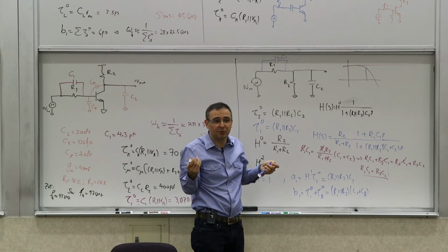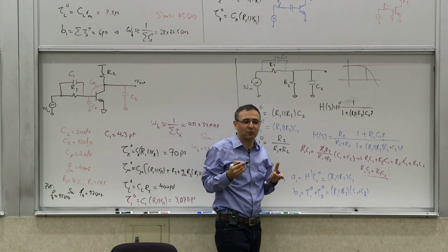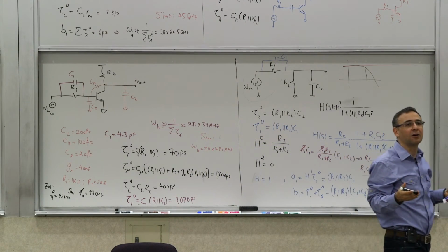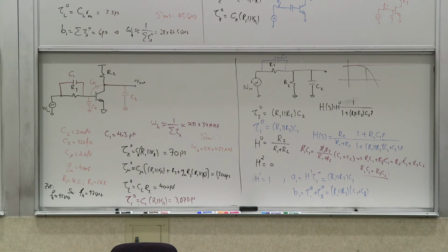And this is another example where it's not just that if you're adding more capacitance, the circuit's bandwidth is going to go down. There are lots of cases where we add. I mean, the example we had last time, right? We started with 1 transistor, and we ended up with 3, which clearly has more capacitances, but the bandwidth significantly improved. It's not just the numerical value of the capacitor. It's where they are connected and what they are doing. Same thing with inductors. They can actually help or hurt.